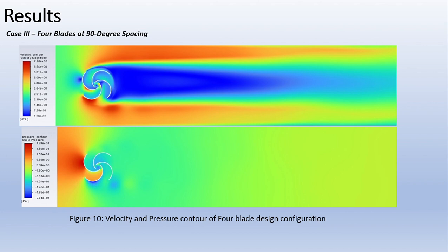Of all the scenarios, the wake flow zone across the turbine buckets and throughout the downstream rotor area is the most intense in this arrangement, and you can see a laminar wake flow region for only the third case. The pressure contour figure shows an increase in undesirable pressure on the upstream bucket convex region. The velocity contour diagram indicates that the air velocity is more significant in the downstream zone, indicating inefficient transmission of air energy to the wind turbine. This is due to the increased blade density, which results in less power generation.